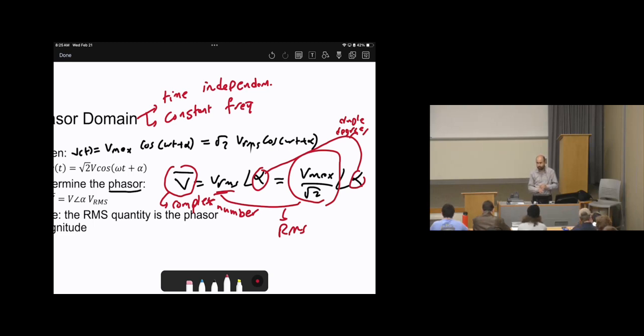What's the advantage of it? The advantage of the phasor domain is that we will no longer see the cosine signal; it will be constants. So it's similar to DC, and you can solve it similar to DC. The disadvantage is that they are complex numbers, and complex numbers mean more complicated analysis. That's why we had a lecture before, like two lectures ago, where we discussed complex numbers, because we are going to use them here.